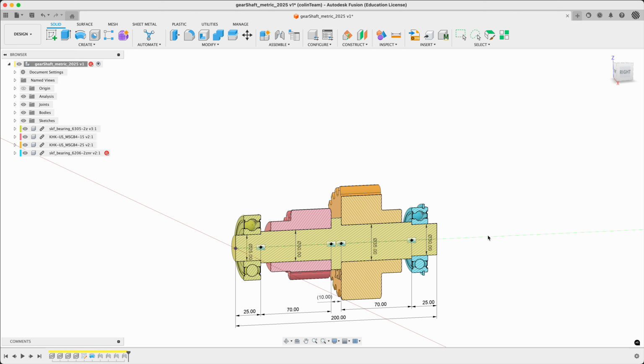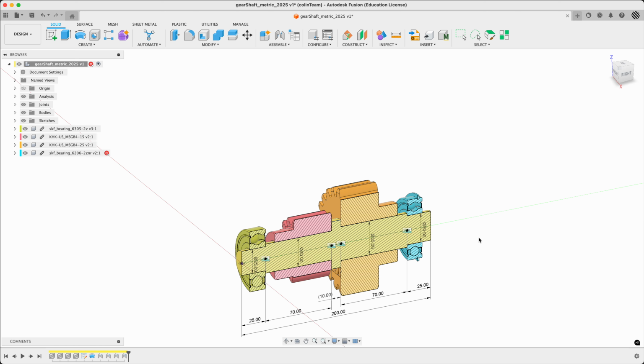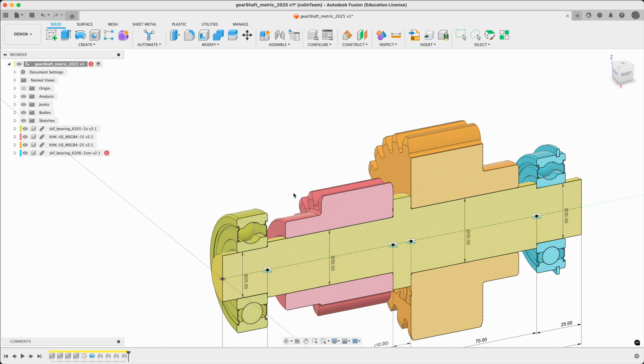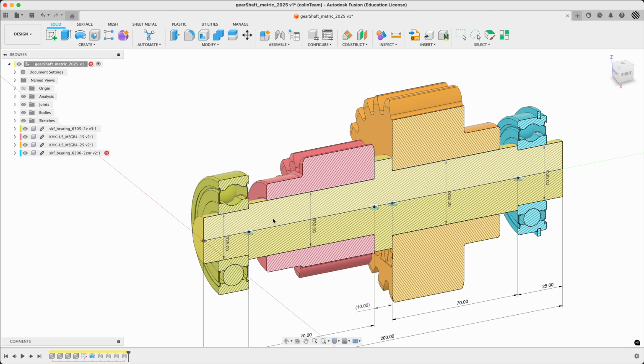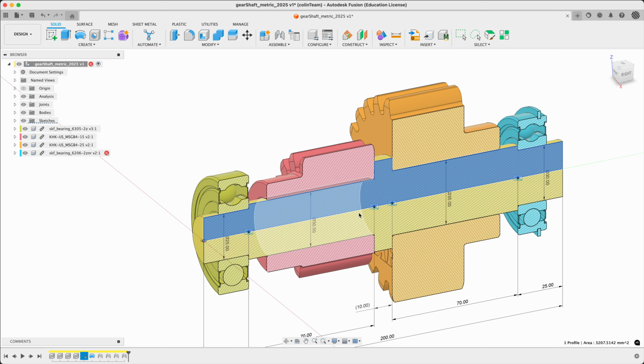Now, there is a choice here. I am gonna do a couple of things, strangely perhaps. I'm gonna do the cutouts in the shaft on this sketch. So chamfers and ring grooves and such. I'm gonna do a separate sketch for what inevitably is coming, the keyways.